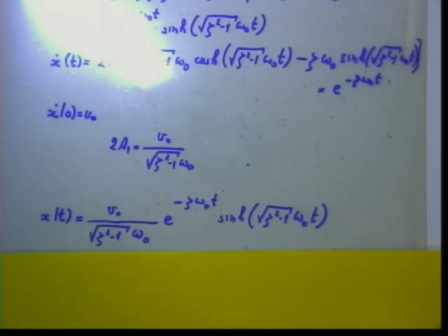Okay? Then we will do main topic of, so to say, center of gravity is beams and plates or something like that, something that have infinite degrees of freedom. However, it so happens that looking into 1 degree of freedom system teaches us a lot about infinite degrees of freedom system. Interestingly, the conclusion is unbelievable. Conclusion is as follows. Beam can be reduced as infinite amount of 1 degree of freedom systems.